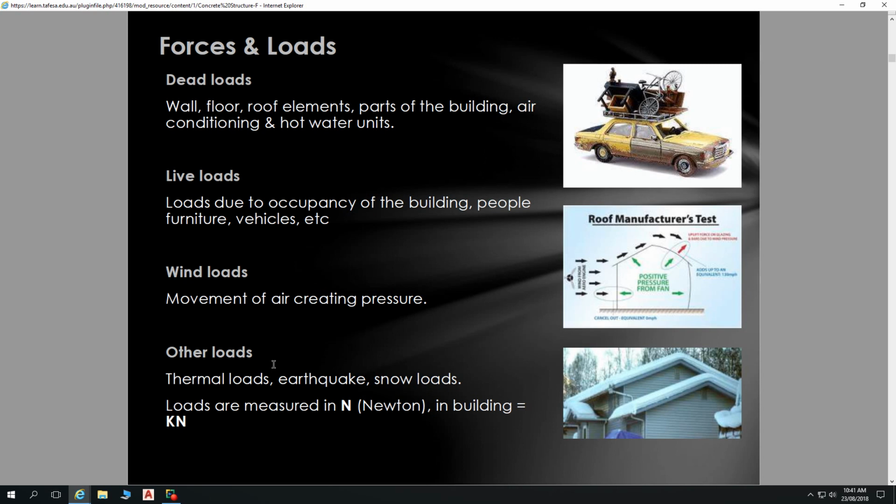Those tie downs, the ability to tie a member to a member, is carried all the way through the frame until it's tied down to our concrete slab. Concrete, typically in residential architecture, gives us this raft on which the building can sit, but it also ties the building down into the ground, stops it getting pulled up and pulled away.